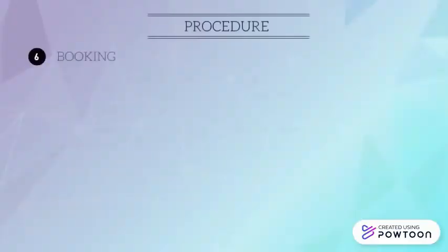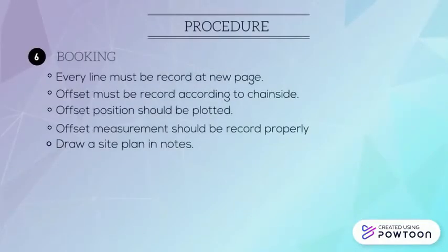6. Booking. Every line must be recorded in a new place. Offsets must be recorded according to the change of site. Offset position should be marked.